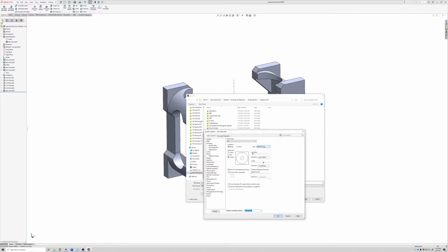So if you get a weird scaling when you import your 3D CAD drawings into slicer programs, you might have accidentally set this to centimeters, millimeters, inches, whatever. You want it set to millimeters for proper scaling. That's what all these slicers assume and print in dimensions of. There's not a lot of extra information in STL files. It's a very simple representation of the 3D object.